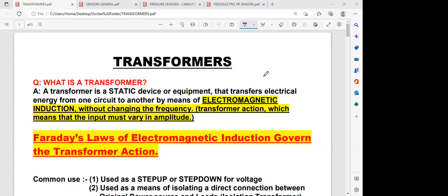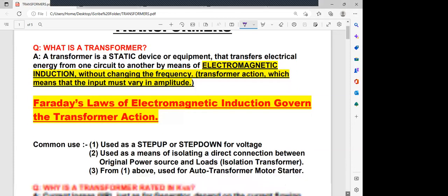Even in your motors, it is a transformer action. How is it a transformer action in your motor? You have your primary. Which is your primary? Your stator coils are your primary. Which is the secondary? Your rotor is the secondary, where we had those steel bars shorted out on either end. As I said, it looks like a firki. So that is acting as the secondary. Basically, that is also a transformer, excepting there you have a rotating magnetic field. Here there is just a changing magnetic field. It is not rotating and therefore will be inducing a voltage into the stationary secondary.